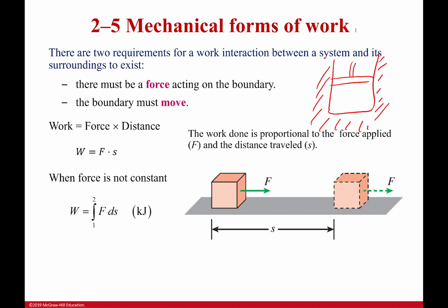Because if I'm trying to figure out how much work a particular gas is doing, like if I put heat into this system, that's going to cause this guy to move. Why does it cause that guy to move? Because the pressure in here is going to increase. When the pressure increases, let's look at it out here. So I'm going to have a circular piston head, and we know that pressure is equal to force over area, right? So if I know the area of this piston head, that means I can figure out the force. So force is going to be equal to pressure times area.